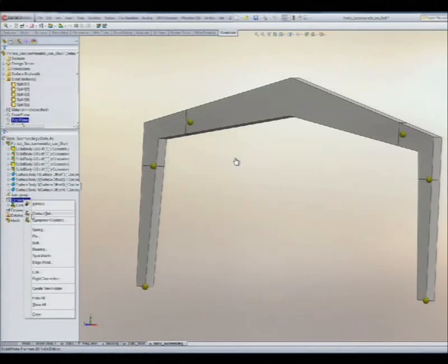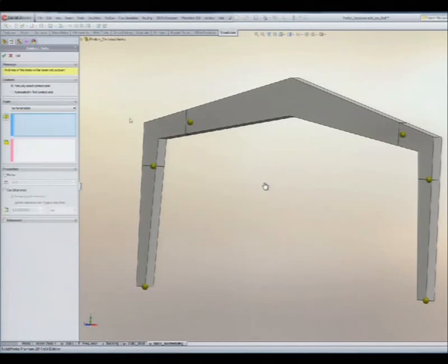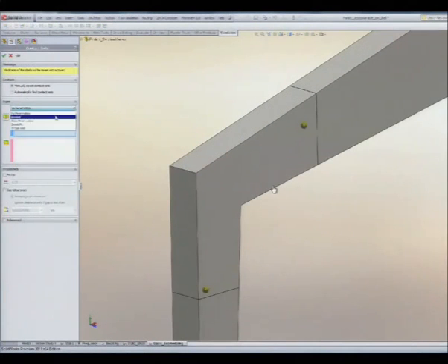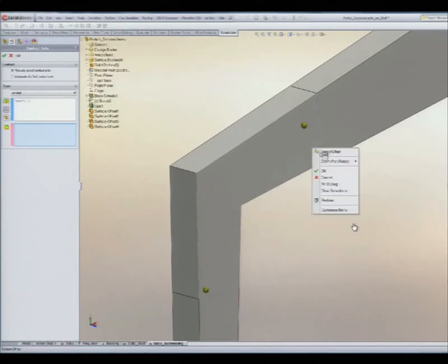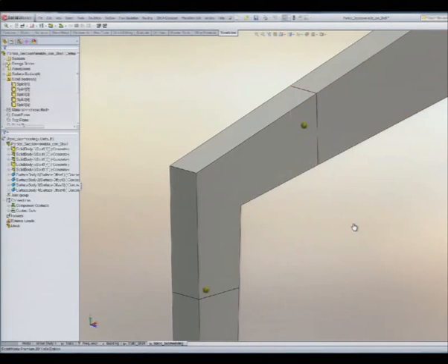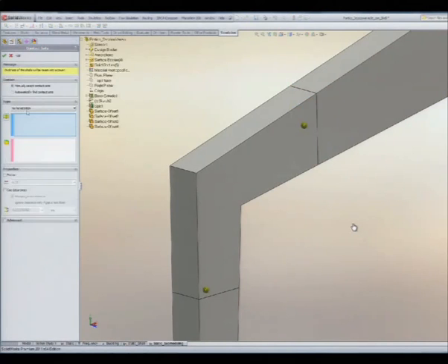The yellow spheres are the joints of the beam, at the end of the beam. So now I have to add a contact condition between the joint of the beam and the rigid surface. Because the rigid surface will be bonded with the solid element, it's not necessary to do anything with the solid element, only with the beam. Of course, I have to do this for every joint in this mixed mesh.